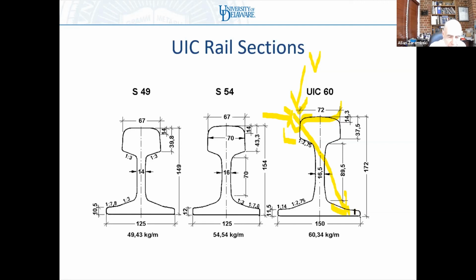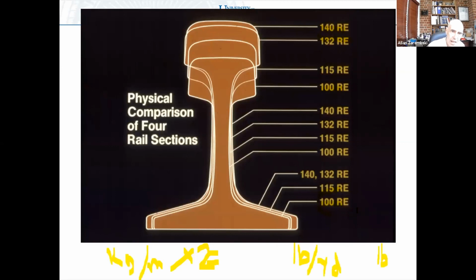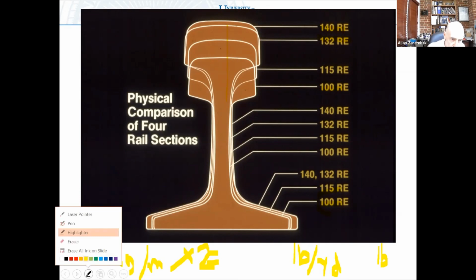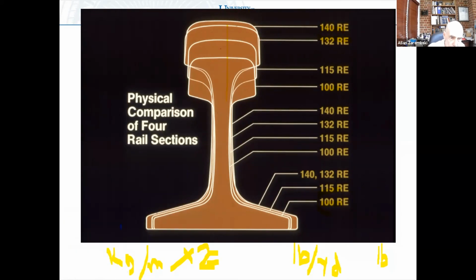Fasteners also do other things like provide longitudinal restraint, which we've talked about before and we'll talk about again. But basically, we want to maintain this overturning stability. So what tends to happen is as the rail section gets taller, the base gets wider.